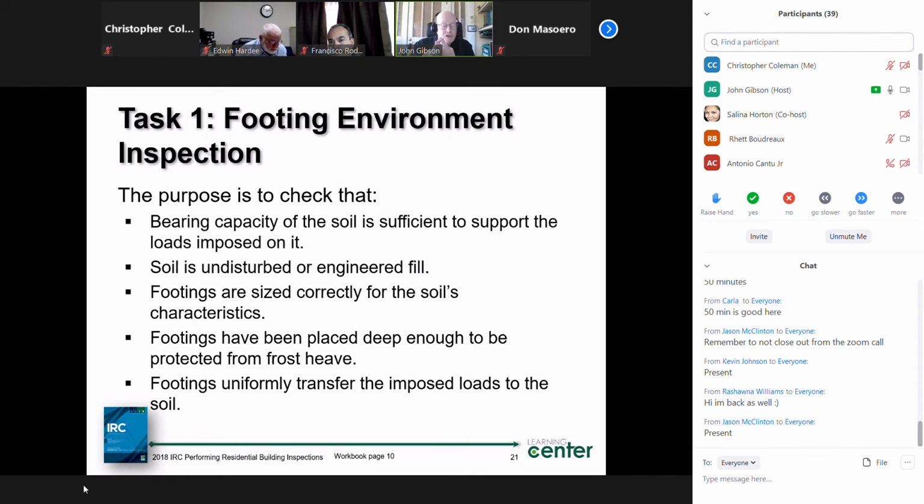But those structures are going to be limited in height, and it's going to be in height above, if you look at the word, grade plane, which is going to say from grade plane, the stories above grade plane, not the basements, the stories above grade plane can't exceed 3. So no more than 3 stories in height above grade plane.